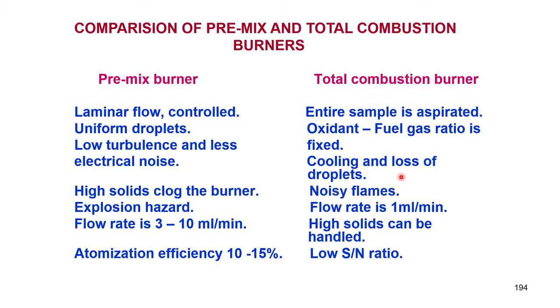The noisy means it is not sound based, but the quality of the flame, sometimes it increases, sometimes it decreases, depending upon how much sample comes. When the sample comes, the flame becomes cooler, so the flame becomes shaky, and when the sample is less, the flame becomes stronger. Like that, the flame is called noisy whenever there is a change in the structure of the flame